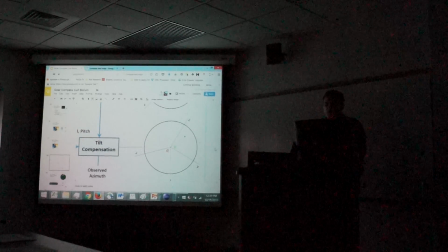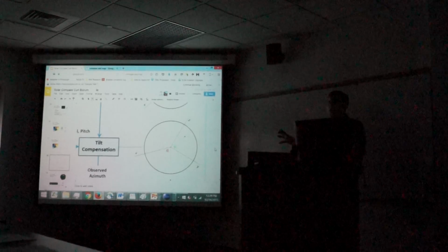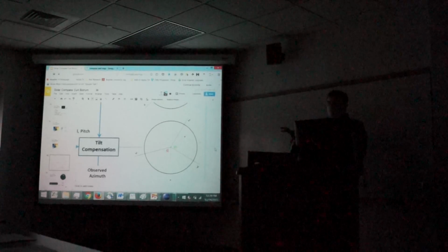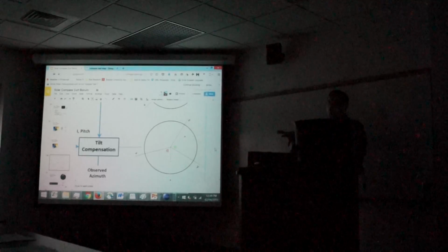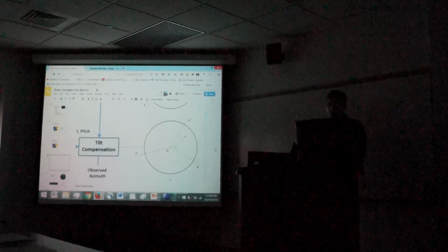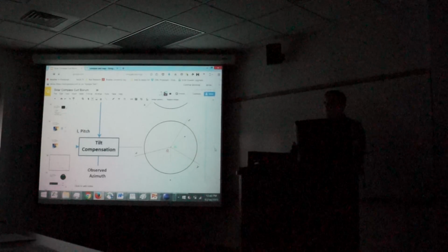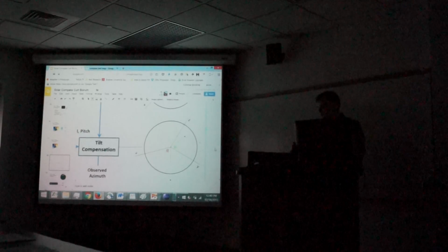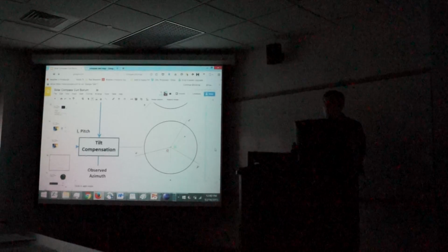and then to correct for the rotation of the robot, it will rotate that unit sphere in the opposite direction of the roll and pitch that the rover is currently at, so it'll undo the effect of rotation on the sun's position in the sky. And that was tested to get all the negative signs correct on the transforms using the three-axis gimbal that was made out of the rotary table and the hand tilt units.